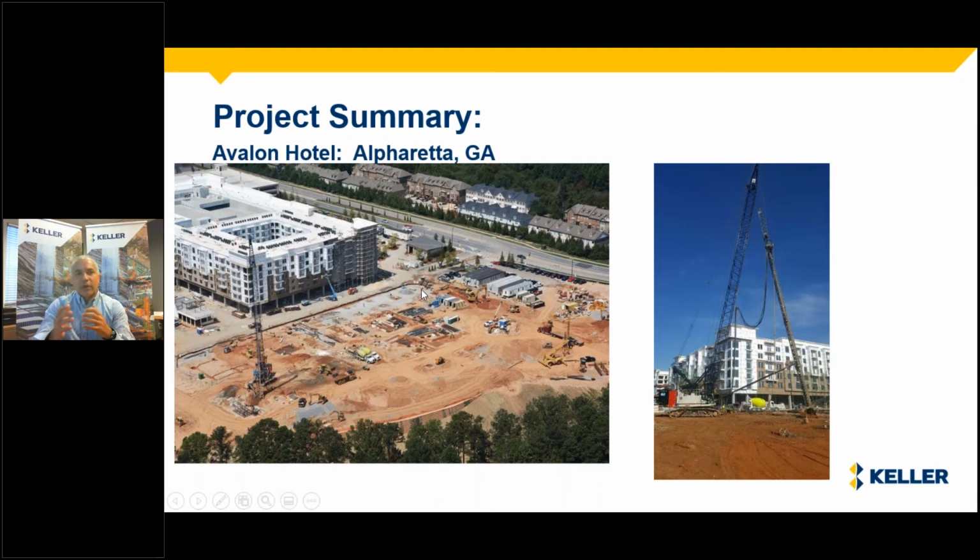So if you're designing a pile and you don't know if it should be 30, 32, or 33 meters long, the load test could be done at the longer length, 33 or 35 meters. Install the strain gauges, and then verify where the load is being dissipated. Therefore, the bottom portion of the pile can be eliminated for the production piles.